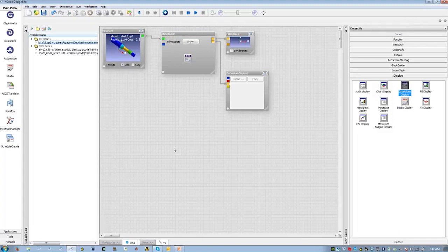And the second thing I have to do is define how these loads are changing. So I have a bending load and I have a torsion load. I happened to actually take measurements in the field of the vertical loads and the torque loads.